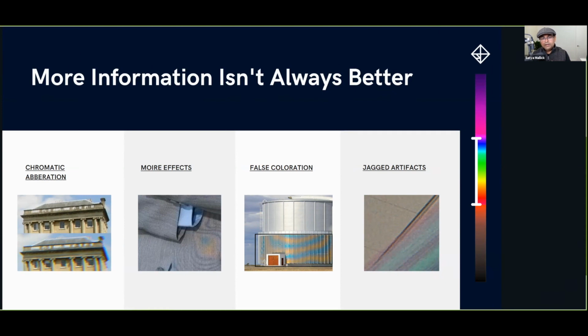You do Bayer interpolation, and you also do tone mapping so that the colors look right. They look like the human eye sees instead of what the camera measures. It's a linear image. If you look at the linear image that comes out of a camera raw, it's very dark. It's not pleasant to look at. So there's a lot of processing that happens when you go from what information the camera records to what's finally produced so that it's visually pleasing. It's a whole process, right?